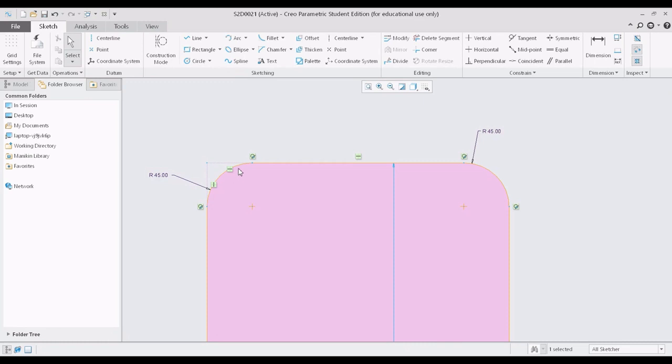In the first fillet, we have a construction line to be seen. This represents the previous corner, whereas in the second option, the fillet with the trim, the circular trim, you will not be seeing the previous reference corner which has been converted to a fillet or a radius. So this is the difference between the general circular fillet and the circular trim fillet.